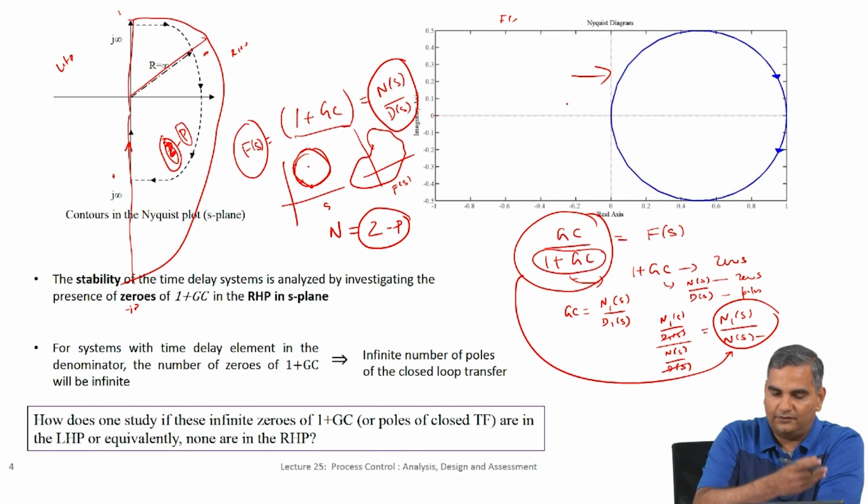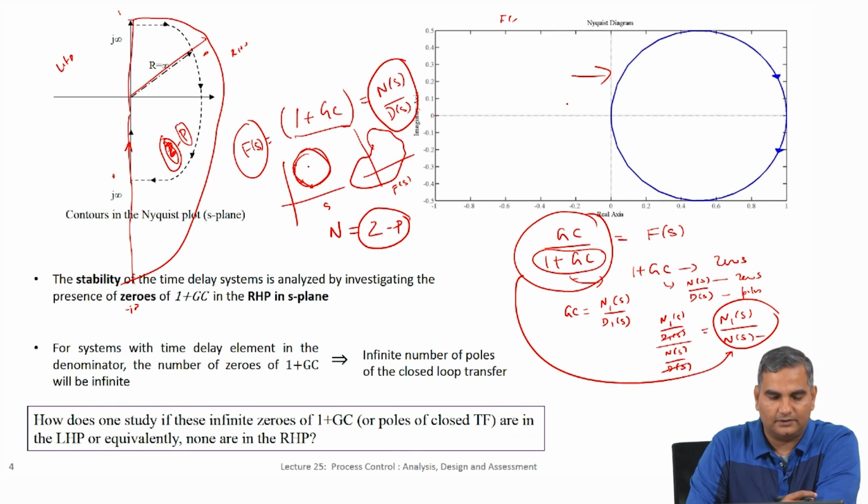So that is a conversion from whatever we saw in the previous slide to a control idea, and the key insight is we know how to characterize how many zeros and poles are there, in terms of a difference Z minus P, inside a closed contour by looking at the number of encirclements around the origin in the F(s) contour.